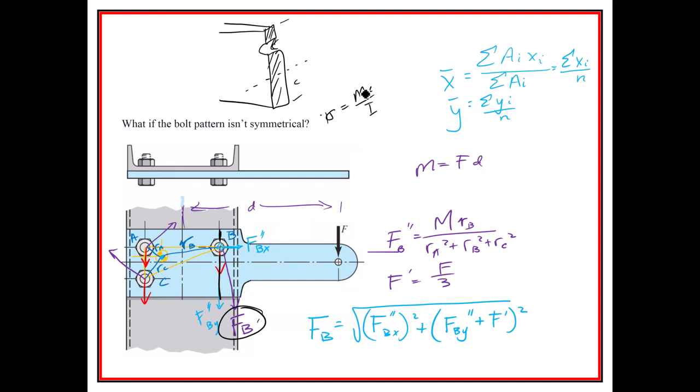The I is going to require us to do a little bit more work because it's going to be about, maybe we call this the Z prime. That's going to be through the center of this cross section down here. And for the I, you're going to need to use the parallel axis theorem to shift where the center is. And you're going to actually have to use it. Well, is that true? Let me think about it.